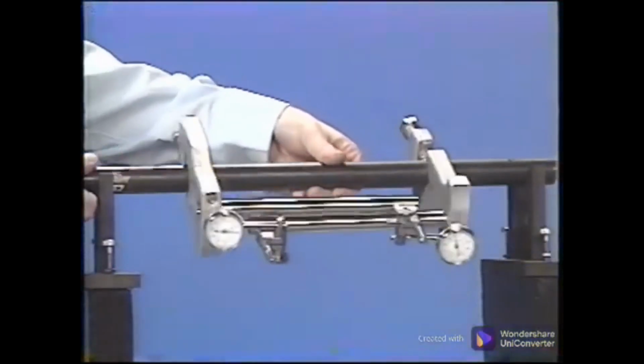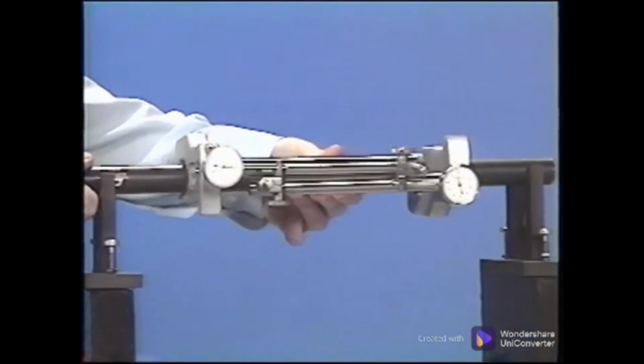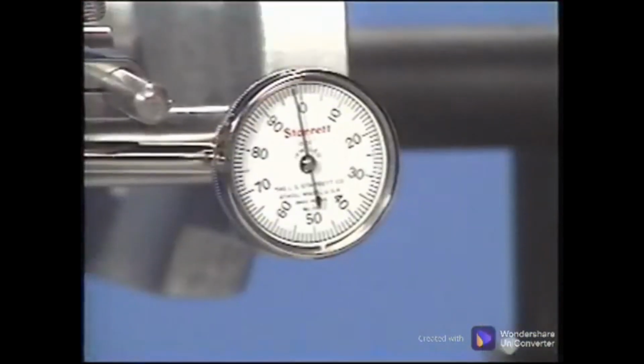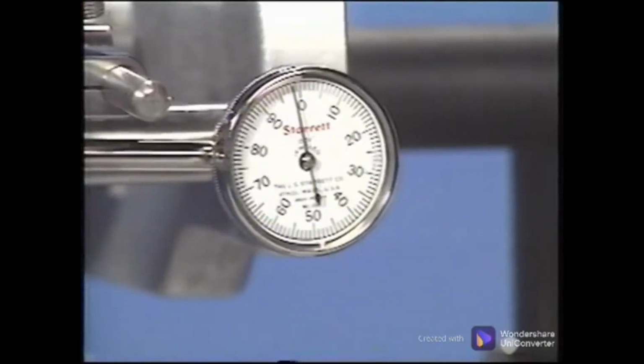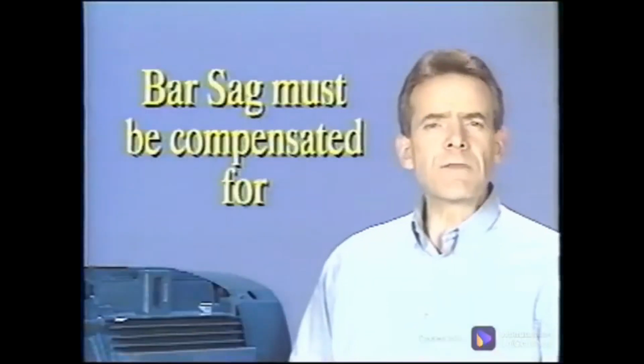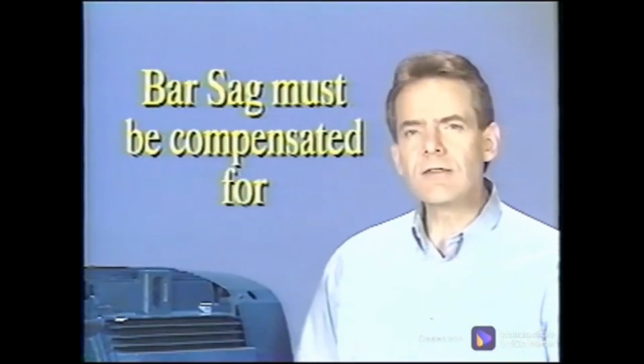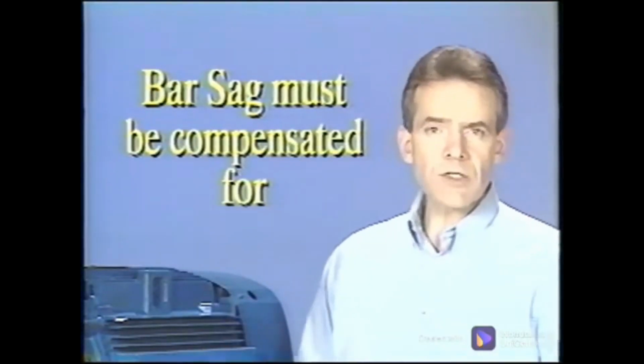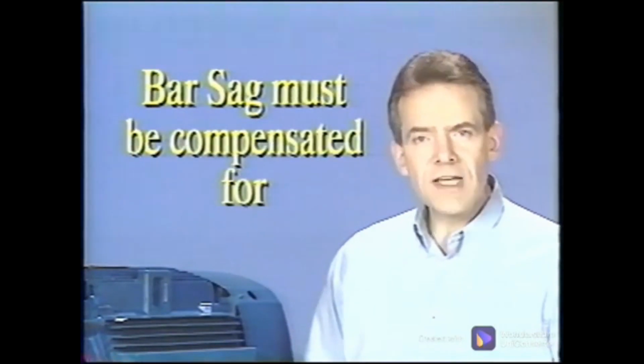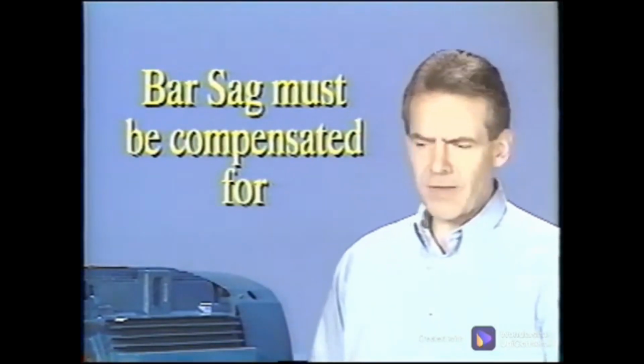When the bar is rotated to the 90-degree position or the 270-degree position, the dial should read half the bottom reading so that they sum to the bottom reading. Remember that this bar sag must be determined prior to the alignment job and must be compensated for in the vertical readings of the face rim method and the reverse dial methods. However, when CSI's Model 8110 alignment fixtures are used in conjunction with the UltraSpec 8000 alignment analyzer, a patented method is used for determining the total bracket sag after the brackets are mounted on the machine.